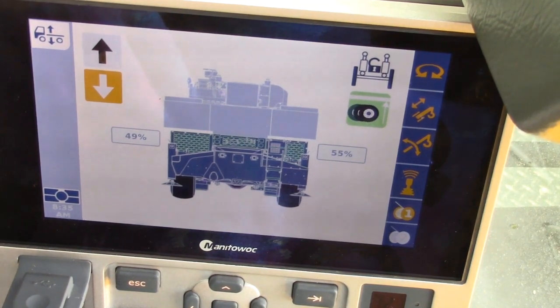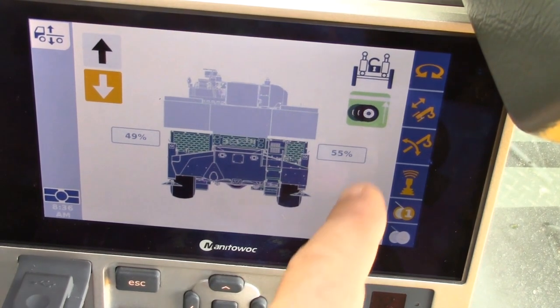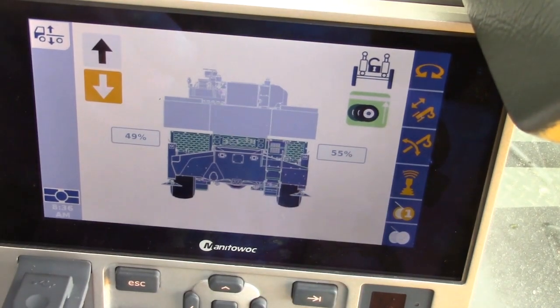Note, it's essential whenever leveling the crane that you must be on a level surface. If the crane itself is on an unlevel surface, one suspension cylinder will not raise to an adequate percentage for the system to then release and be at ride height. Note, we never lock the drive capabilities out for ride height, and we do use all 3 suspension positions. I will show now that the RCL has been properly configured, that we have control of the suspension.